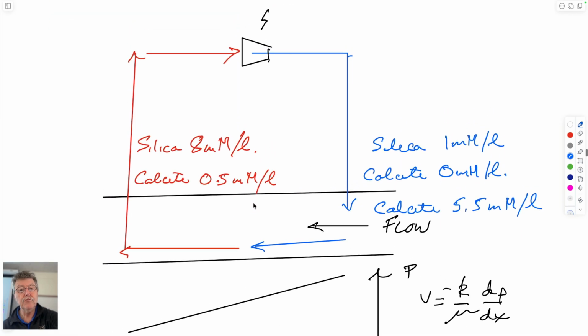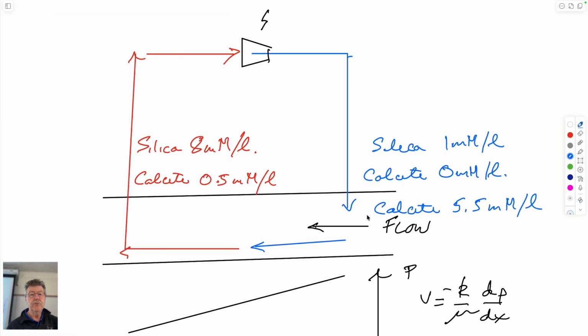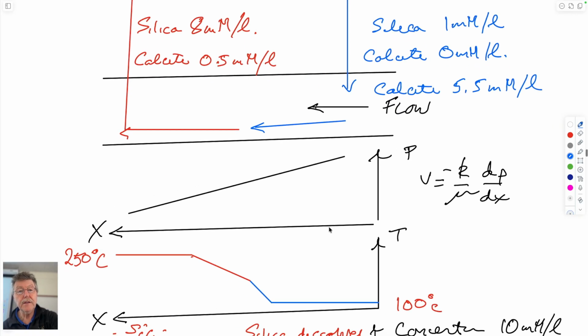So if you look at a realistic reservoir, the reservoir here is where you re-inject water into the system. It flows across the reservoir, is transferred from cold water as it comes in to being hopefully hot water as it comes out. It's taken out of the system hot, flashed to steam through a turbine to generate electricity, and then condensed and put back into the reservoir. So if you go through that cycle, we kind of have everything we need to be able to say what's going on with that. If we look at the transmission across the reservoir, we know how to do that.